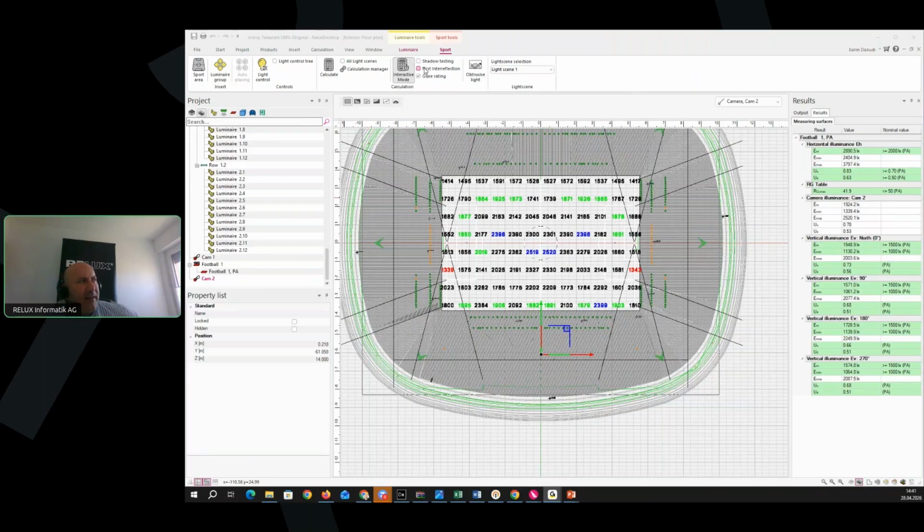If you activate the first interreflection and shadow testing, then the result will be close to the real results from the ordinary calculation path. But for rough work in progress, it's enough to calculate with the direct part. This question is also answered.